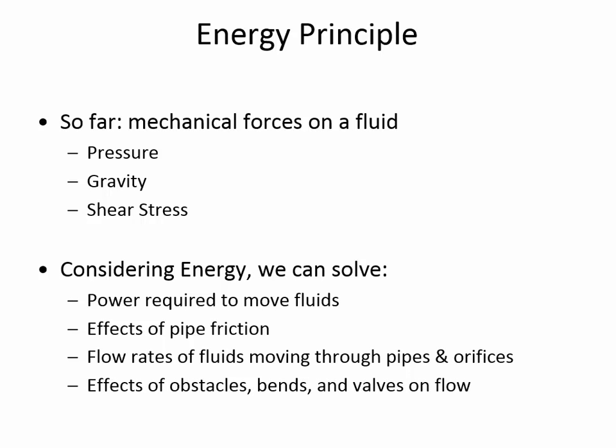And then also, there are these things called local losses, and that's what we're going to do in the lab next Tuesday. And I showed you on the pipe rack that when you have a pipe that is making a gradual transition, there's going to be less energy loss as the water flows around a nice gradual bend like that than when it's a sharp 90-degree angle and the water's having to make that turn rapidly. It induces a lot of turbulence. There's a bigger pressure loss because that turbulence causes a loss of energy.